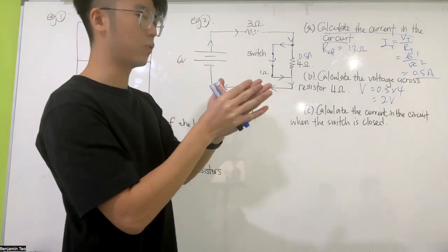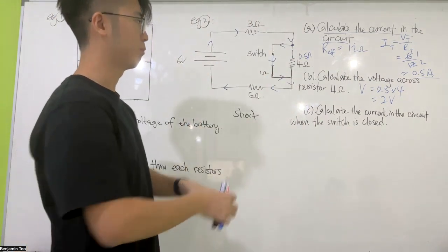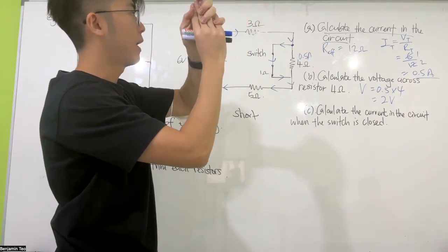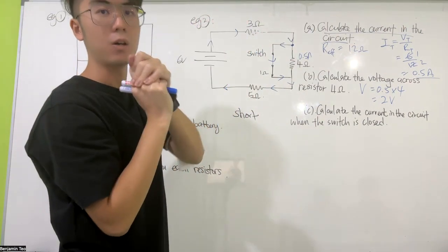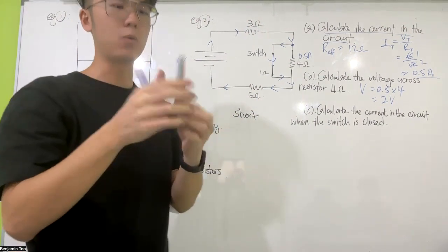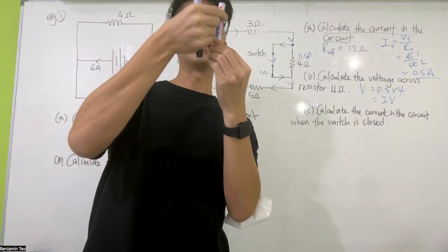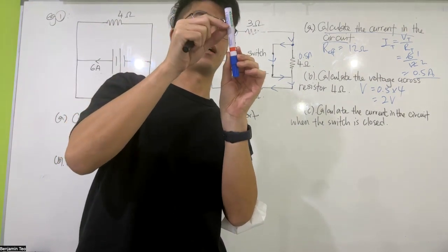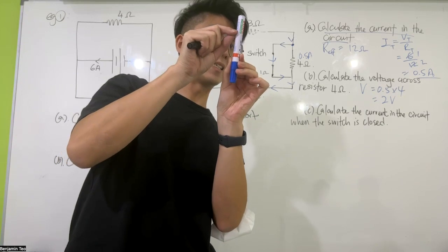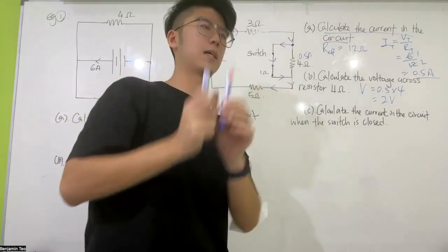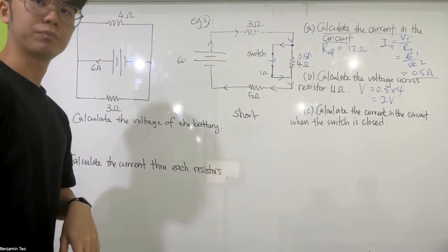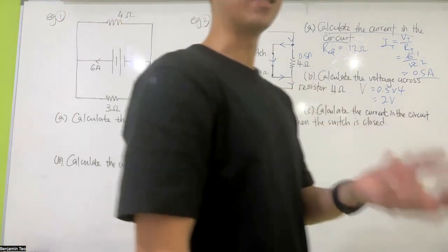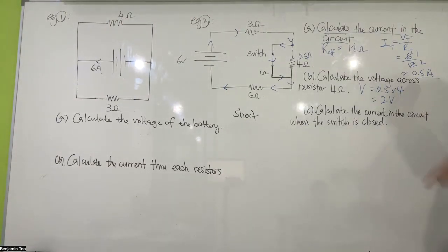Especially when you have massive wires all bunched together, there's a high chance of causing short circuits. Or maybe the wire's outer layer, the rubber insulator, is damaged already. It wears out, so you can see inside, the wires touch and you create a short circuit. It's the main reason causing fire in aircraft, and in many electric places.